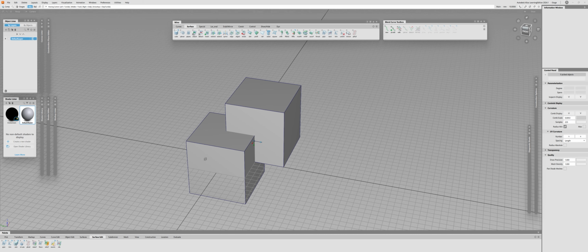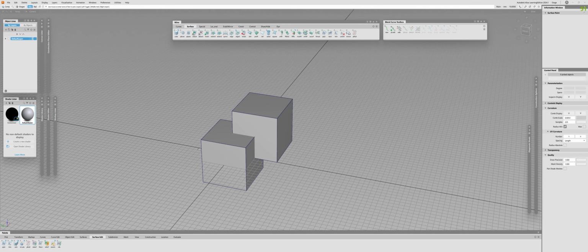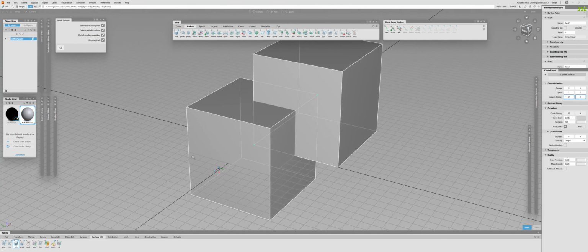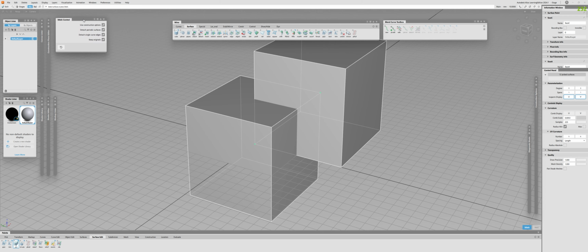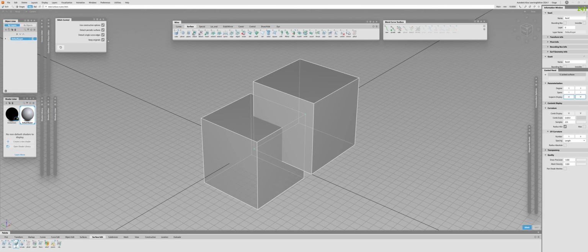So let's do that. In the Surface Edit, we have this additional group, which is stitch and shell unstitch. So I will just select everything and perform the stitching operation. As you can see, there is a small amount of options. We are using construction options.